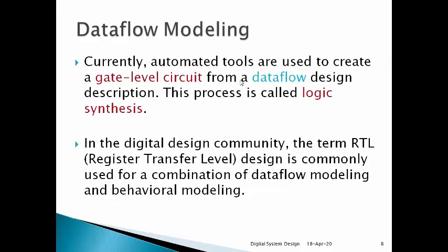Now, logic synthesis is a tool which is used to create a gate level circuit from a Dataflow design description. Here you see that we are designing at the Dataflow level, and through the logic synthesis process we can create a gate level circuit from the Dataflow design. Now RTL, known as register transfer level, is commonly used for a combination of Dataflow modeling and behavioral modeling.